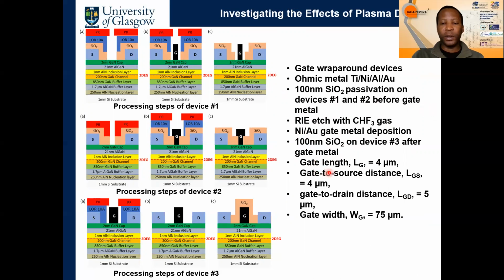The device dimensions are a gate length of 4 micron, gate to source distance of 4 micron, gate to drain distance of 5 micron, and a gate width of 75 micron.